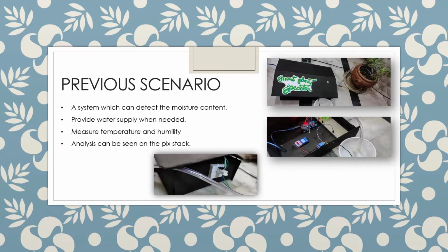So in the previous semester I developed a system which can detect the soil moisture content of the soil, and I showed that on a monitor, by simply using a soil moisture sensor. And when the reading gets below some threshold, I provided a water supply system that will water the plant as soon as the command gets processed.